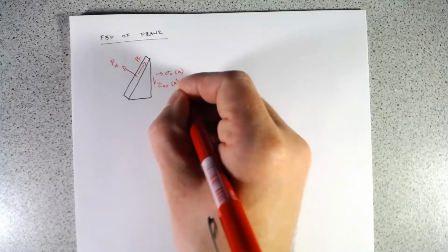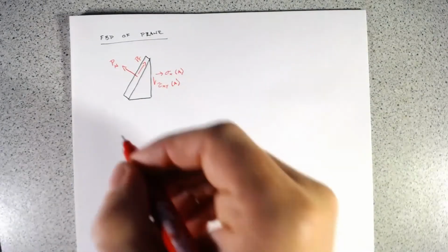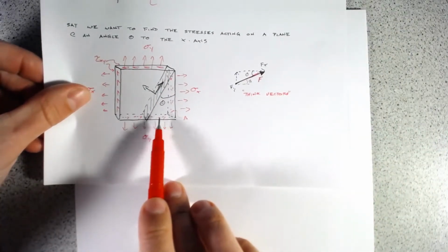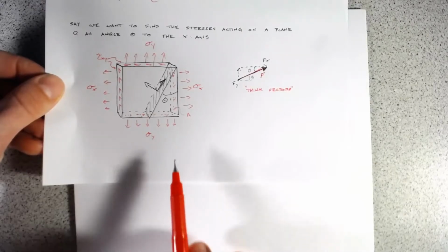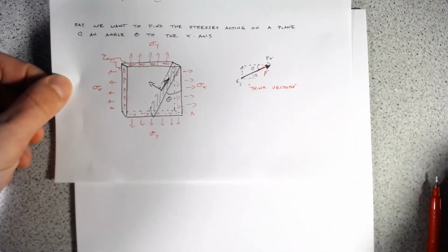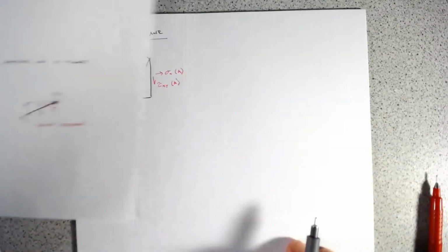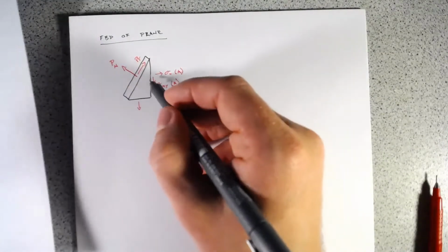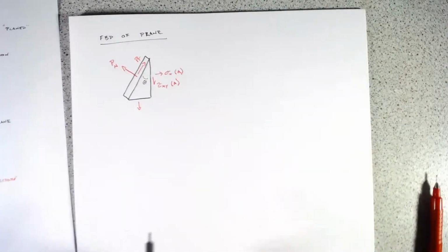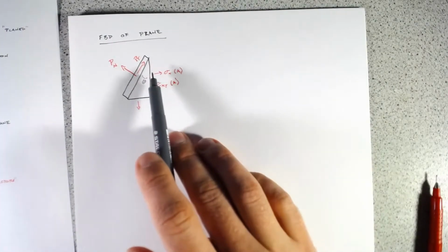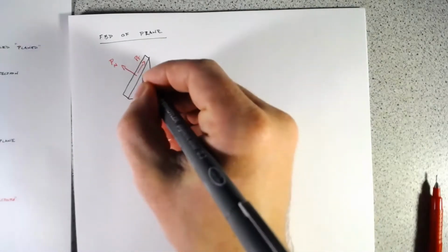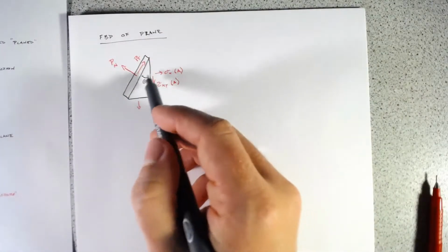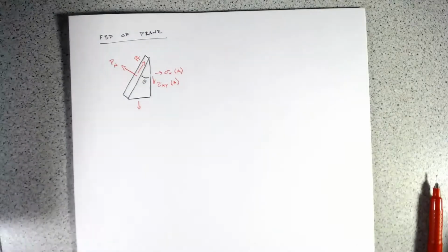xy times A. Now when we go to the y direction, like I said, we're going to have a little bit smaller area here, so we have to reduce that accordingly. And this is really the same as, if we use our trigonometry, and we have some angle theta here, the tangent of theta equals the opposite over the adjacent, so we can solve for that and get our equivalent area down here.